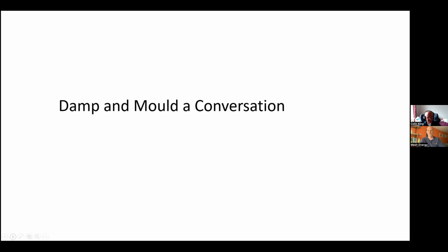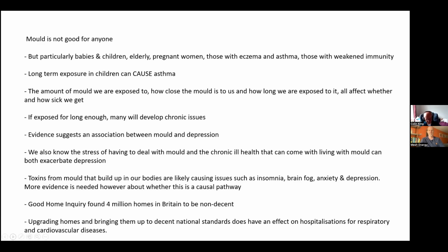Basically we're looking at the issues around mould and damp. I don't like the term damp because it doesn't explain the whole issue, because damp is a term for many things. It could be old damp in older buildings, which is historic and has been there a long time because of the inherent structure of the building, or falling damp because of leaking gutters, or rising damp because of a failed DPC, or penetrating damp because the wall isn't maintained, or internal damp because of high levels of relative humidity within a building.